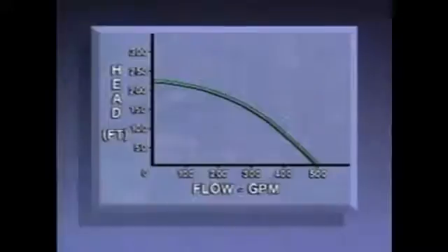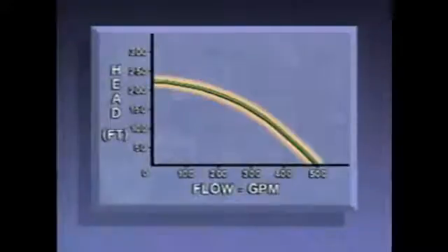One way of examining a pump's design characteristics is with pump curve graphs. This one shows the pump's head curve, which represents how much head or pressure the pump should produce for various flow rates. The curve shows that the amount of pressure that this pump produces decreases as the flow increases. Since this curve represents what is expected of the pump, it can be compared with actual values for total head and flow to see if the pump is performing the way it should.